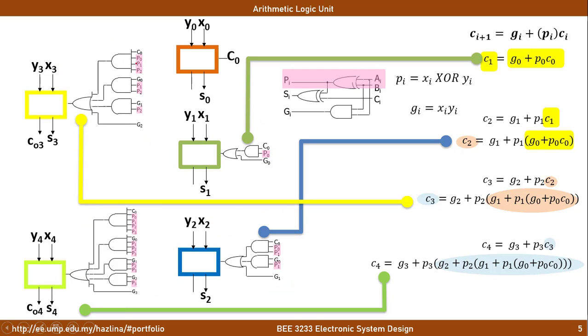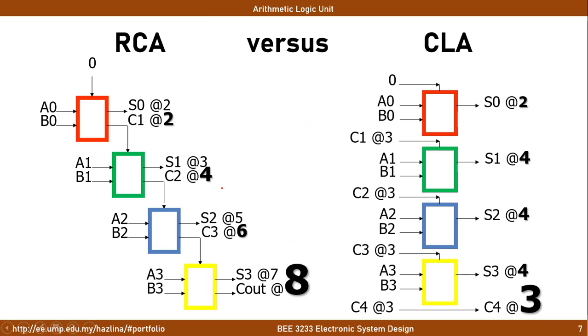These are the pink elements, which are equivalent to Ai exclusive or Bi, the current state, which is being fed into the first, the second, the third and the fourth addition cycle. This is an example of the generated bit Gi, which is being fed accordingly as shown here.